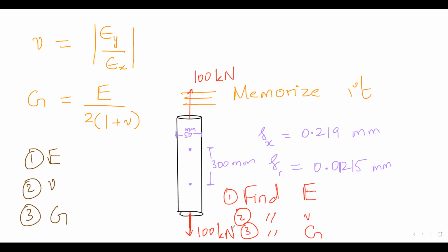Should I help you a little bit, everyone? Or you have already started? So elastic modulus is equal to stress over strain. I will find stress, force per unit area. Then I already know the strain, which is change in length 0.219 millimeter divided by 300 millimeter.